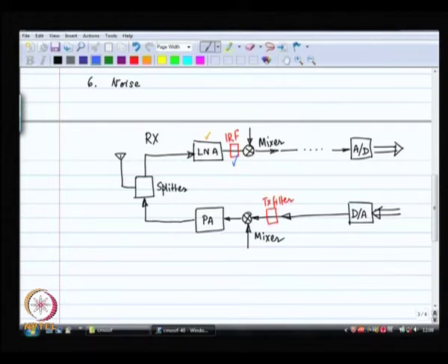Then there is the mixer. We talked about the mixer. Of course, you have in phase and quadrature phase signals. So, you have to make a quad mixer or rather a quadrature mixer, right, and for a quadrature mixer there are several architectures that you can pick up. This is the Weaver architecture, for example. You can use the Weaver architecture and build a quadrature mixer.